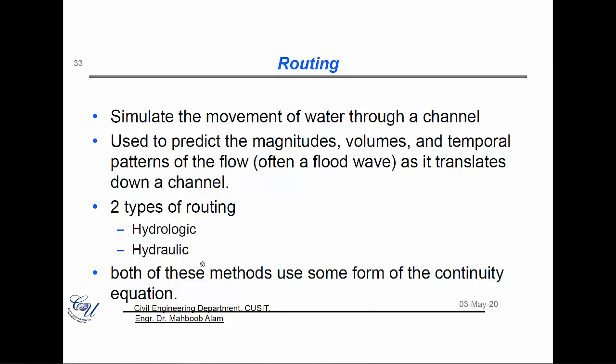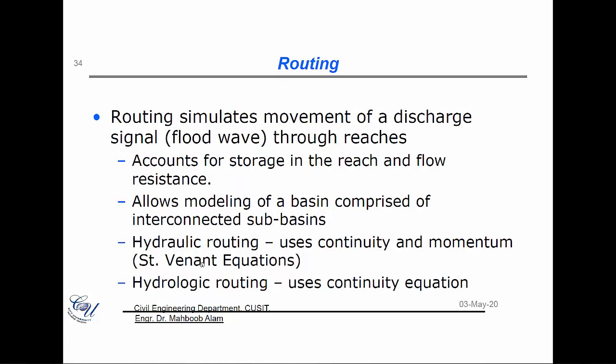Both of these methods use the continuity equation for their calculation, plus some additional information that we will be looking at. The important equations would be the continuity equation and also the Saint-Venant equation if we are using hydraulic routing.